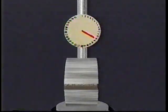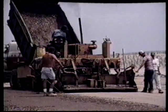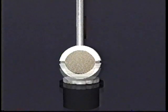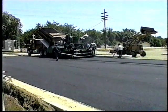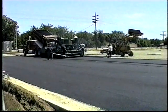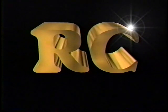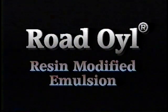As you will see, road oil resin modified emulsion is in a category all its own when it comes to bonding power. With proper aggregate selection and attention to mix design, road oil pavement mixtures demonstrate stabilities that approach the strength of Portland cement concrete while maintaining the flow or elasticity characteristic of asphalt concrete pavements. Today, in addition to Portland cement concrete and asphalt concrete, we have resin concrete, or RC, a material category made possible by the road oil resin modified emulsion technology.